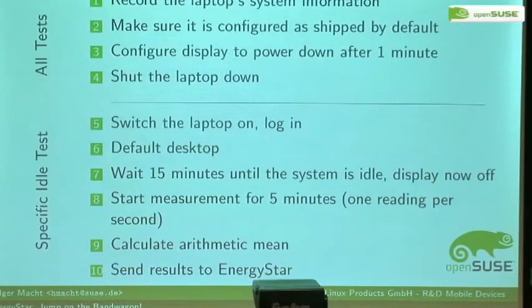Then you start your measurements for 5 minutes with 1 reading per second, and then you evaluate your measurements, so you have an average power consumption. And if this sequence was done under laboratory conditions, then you can send the data to Energy Star, and they will most likely include your product in their database.